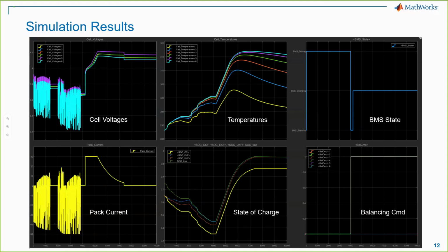As you can see, this single simulation helps us evaluate most common BMS algorithms, such as current limit calculations, state machine transitions, state of charge estimation, cell balancing, and interaction among these algorithms. Software developers can develop many different test scenarios and validate software logic through the desktop simulations. This model-based design approach allows them to make rapid design iterations without going through costly hardware testing. More importantly, the closed-loop simulation of BMS can be used by electrical engineers to evaluate interaction of battery pack with charger and power inverter.